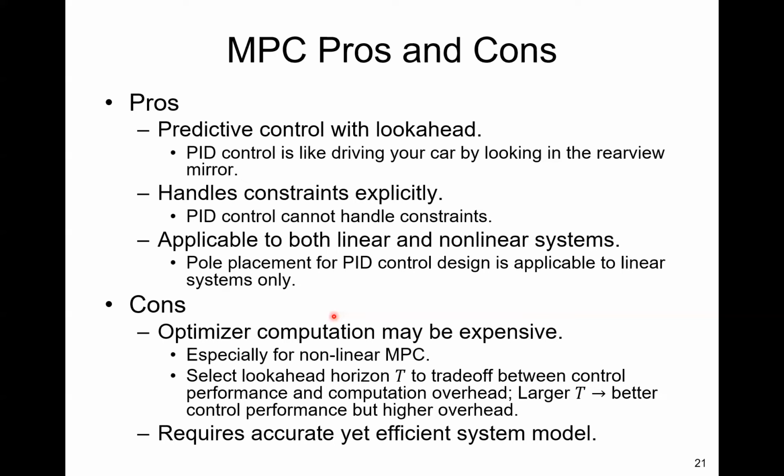There have been a lot of advances on the algorithm side and also on the hardware side, as high-performance ECUs are used more and more in cars. The computing power is also increasing. So the combination of algorithm and hardware advances makes MPC applicable to automotive systems. And also the look-ahead horizon T can be selected to trade off between control performance and computation overhead.